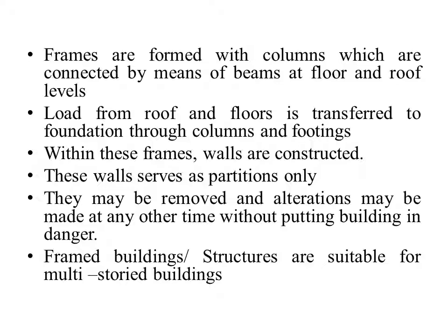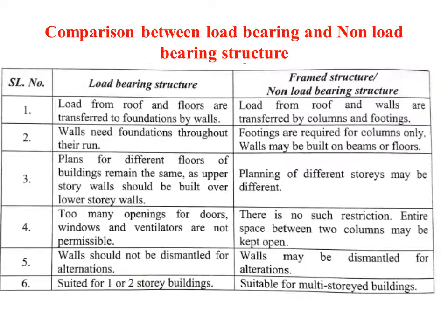Within these frames, the walls are constructed, and these walls serve as partitions only, that is, they are not taking any loads. They may be removed and alterations may be made at any other time without putting the building in danger. Usually, framed buildings or structures are suitable for multi-storied buildings.